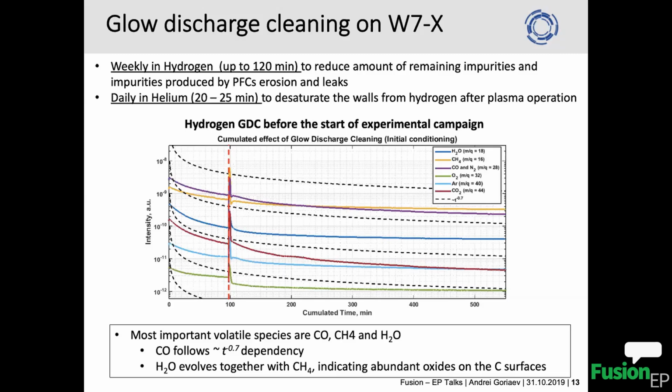I mean, it can be really complicated. For instance, for W7-X, it's super tricky to calibrate it because, first of all, the mass spectrometer is located in the pumping duct, a few meters from the main vacuum vessel. So it's differentially pumped, and we have to take into account all the conductance of the pipe for different species, all this that you mentioned before, plus there is the influence of the magnetic field on the quadrupole, so it has to be properly shielded. Yeah, it can be as complicated as you want it to be, depending on your application.